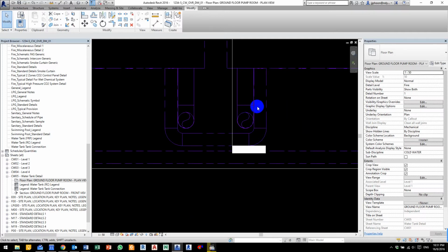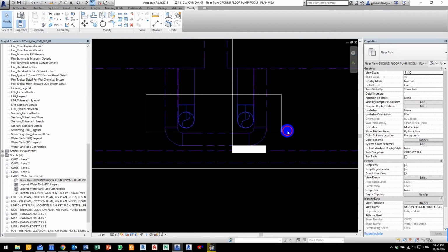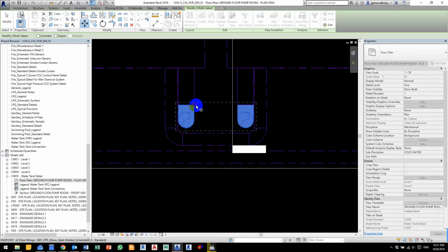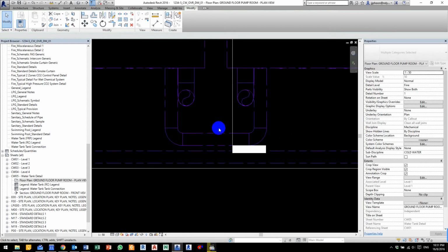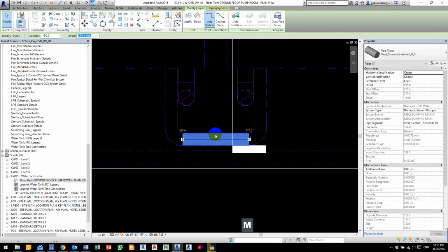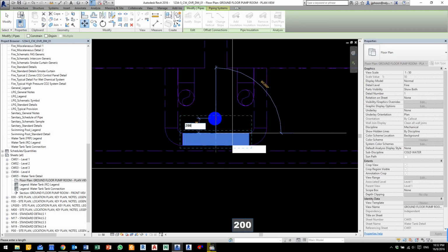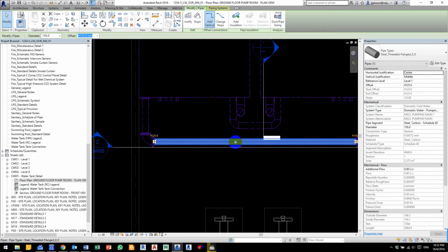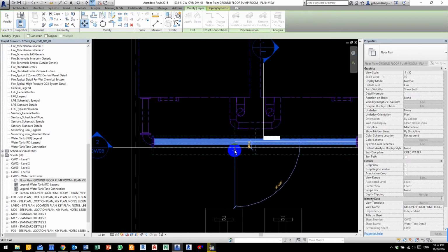Now we're just gonna adjust our pipes a little to make way for the outgoing pipe. So the first ones which I want to move are my 2 overflow pipes. So I'm just going to draw a box selection to select these two. MV to initiate move. Click once on this edge and just move it in by, let's say, 300 mm. And I'm going to move my balancing pipe in by 200 mm. I'm going to move my incoming pipe away by another 200 mm.